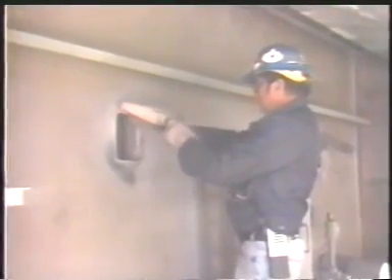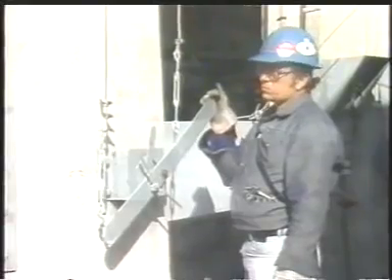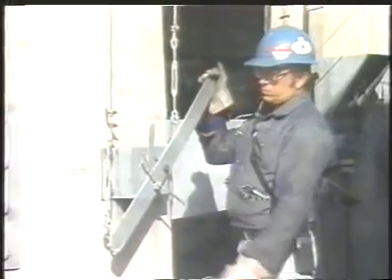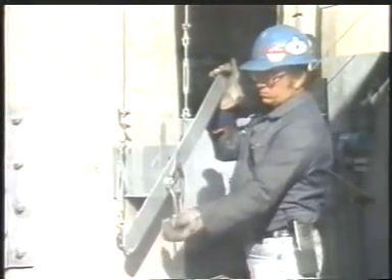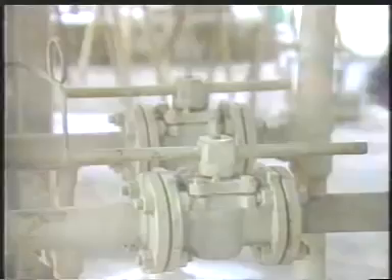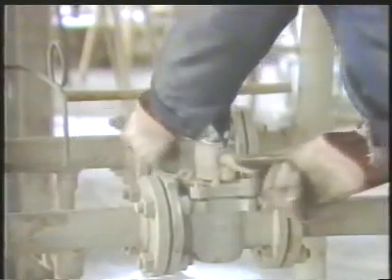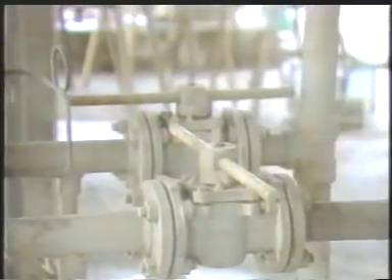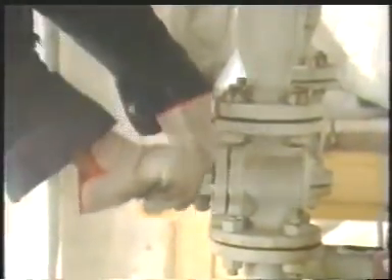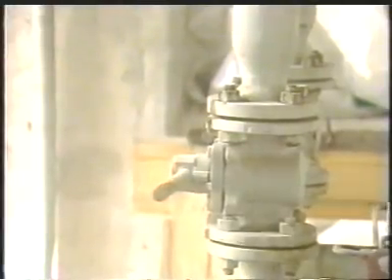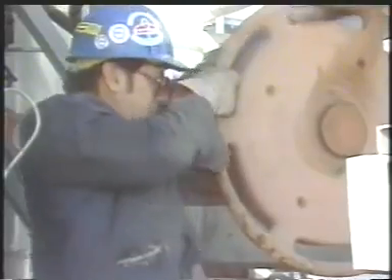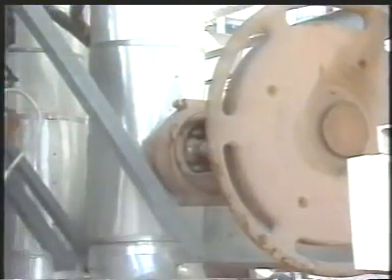Process circulation is continued to cool down the tube slowly. Next, you open the stack damper and air registers to purge the furnace. Then block the fuel systems, including the burner and regulator valves. And when the furnace is cool enough, stop the process flow and block the process systems.